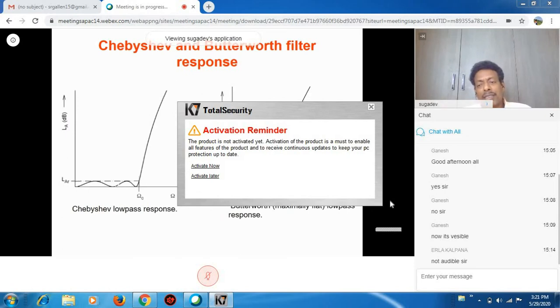But if you take the DSP filters, you might have some knowledge on the DSP filters, right? There, it's a software kind of thing. So with DSP filters, you can have a higher value of n. You can very easily design a filter for n equal to 100, n equal to 50. But the signal loss will not take place because you are just doing a delay element. It's a cumulative addition and multiplication we use in a DSP filter. So losses will be very small in a digital filter.